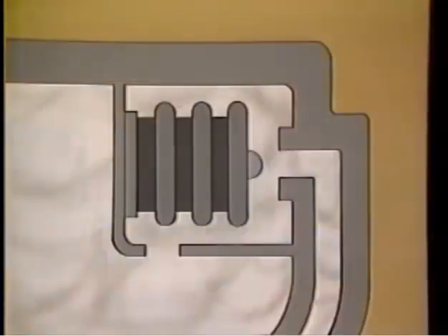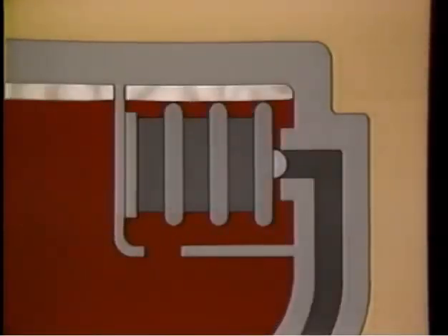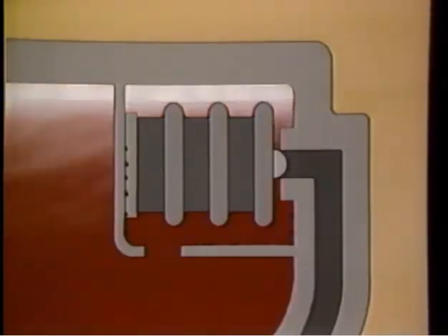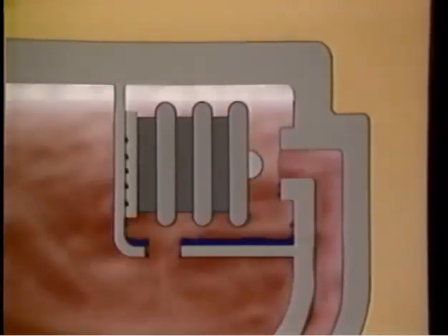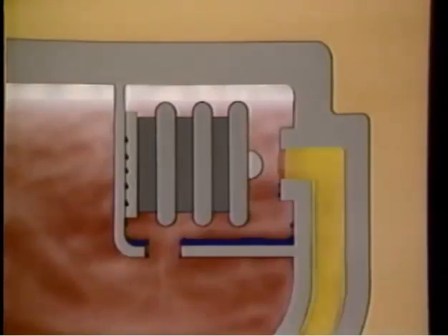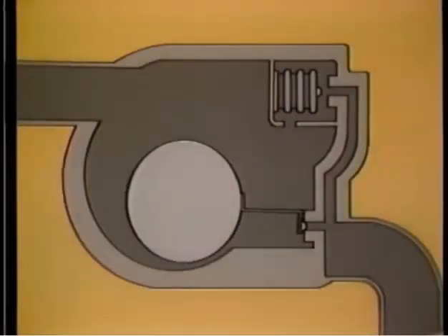The bellows responds to temperature change. When this space is filled with hot steam, the thermostatic valve is closed. Non-condensables, such as air, mix with the steam and cool the space near the top of the trap. When the bellows element cools sufficiently, the thermostatic valve will open and vent these gases into a passage leading to the trap discharge. At startup, the float is down, the float valve closed, and the thermostatic valve wide open.